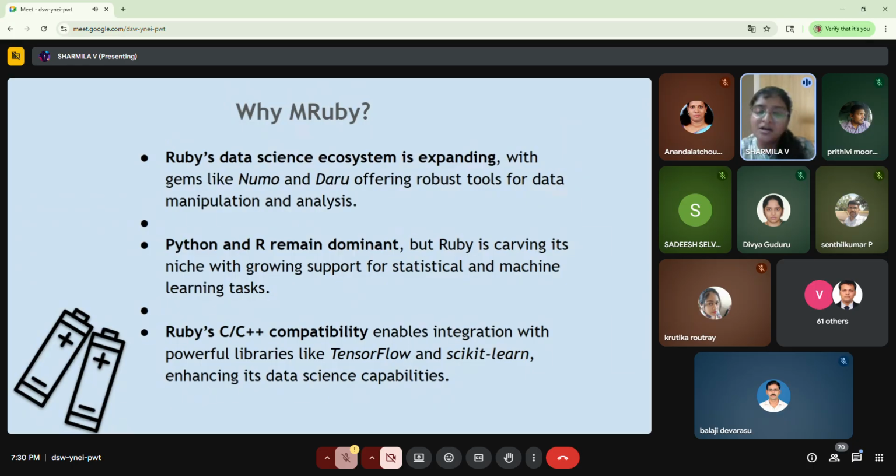And we have the HTTP gem also to help with the HTTP protocol and HTTP communication within the system as well as with the cloud. It provides the client server support for the system. This gem is used when we implement them. When we see the BMS models in electric vehicles and stationary energy storage, they will be sending real-time data to the IoT dashboards to display the efficiency of the system. There we would be using the MQTT and HTTP protocols, and we use these mruby gems to implement those protocols.